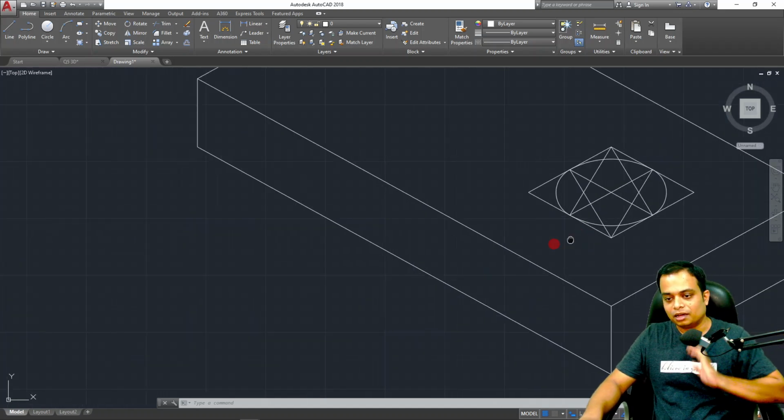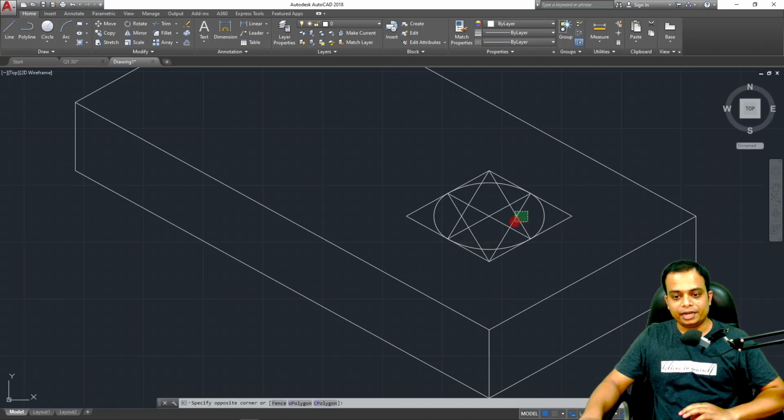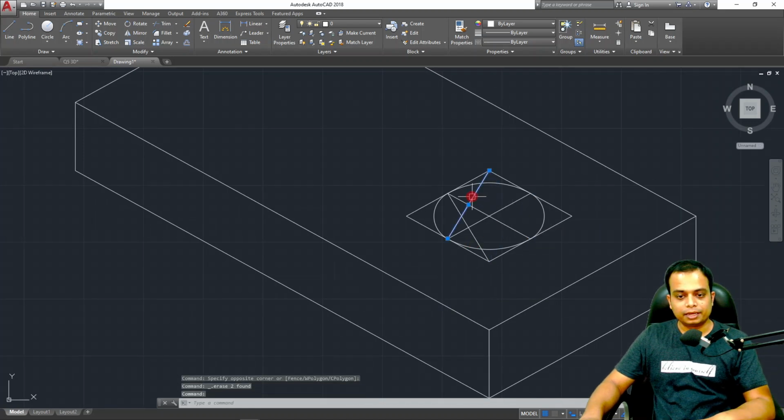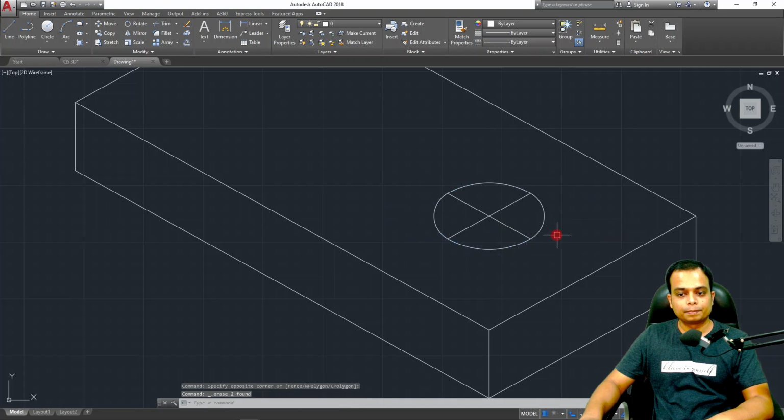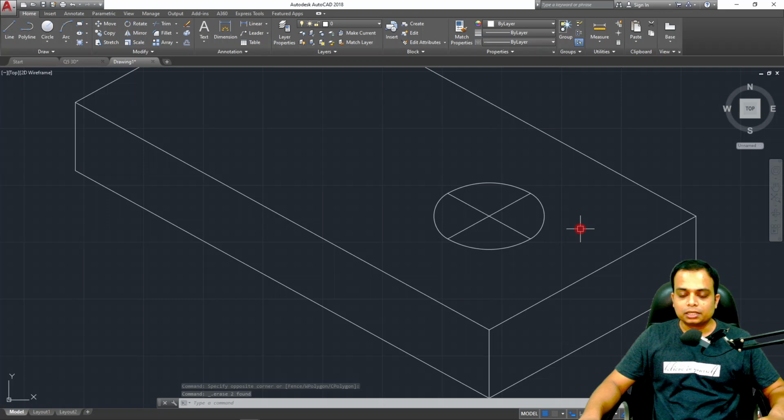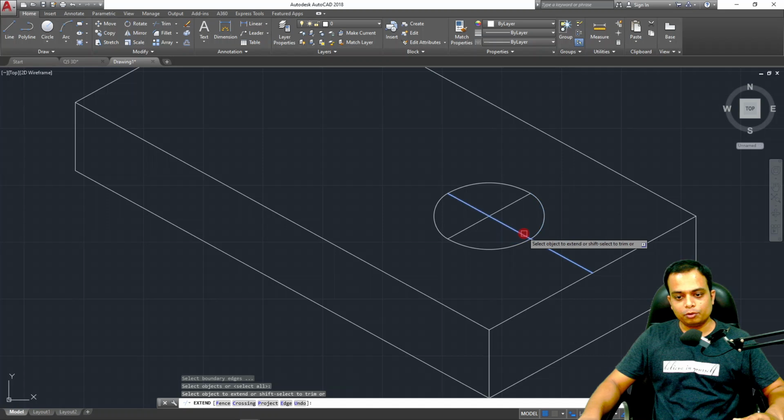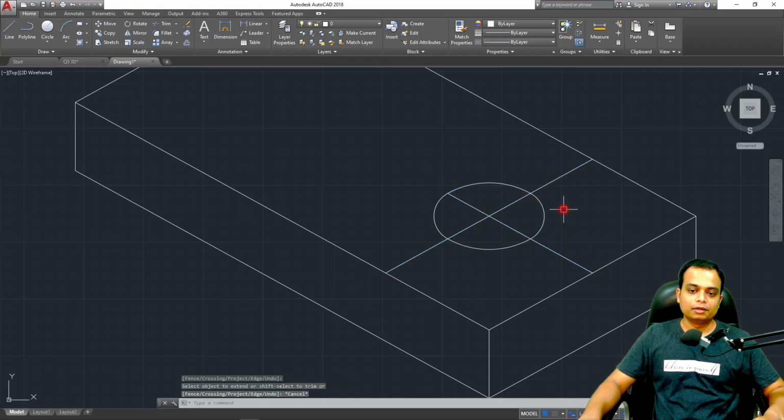All right. Now what to do? I think better to get rid of this construction. Now what I'll do is create the semicircle over here. How to do that? Use the extend command, and I'm going to extend these lines. This line is going to be 25, that's 25, and that's 25. We already know that. Here we need to create a semicircle.